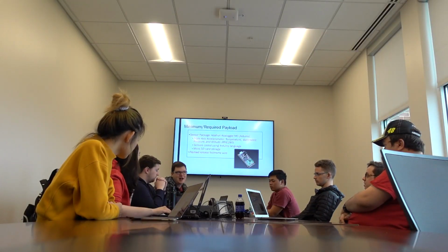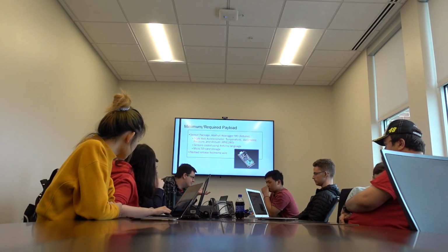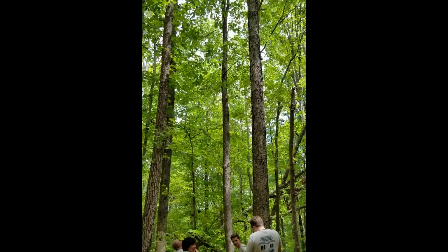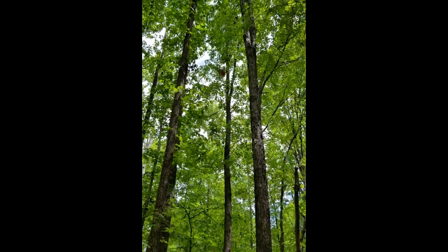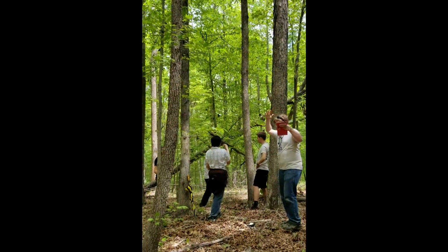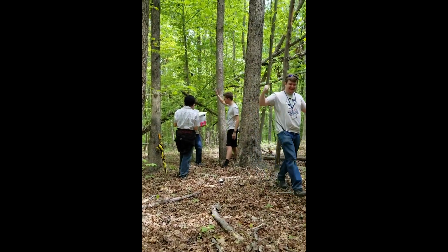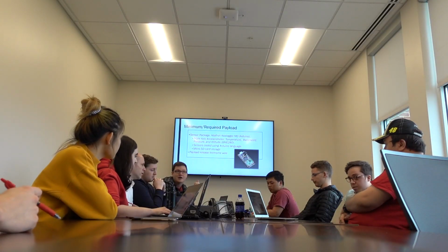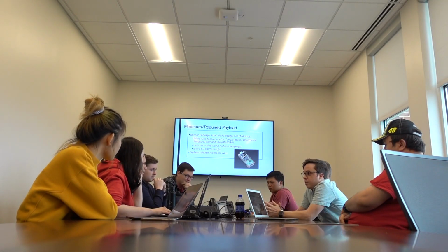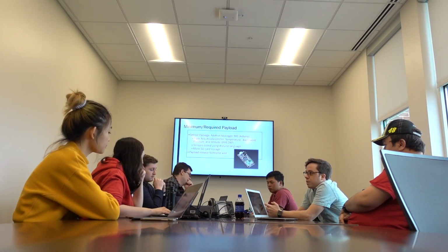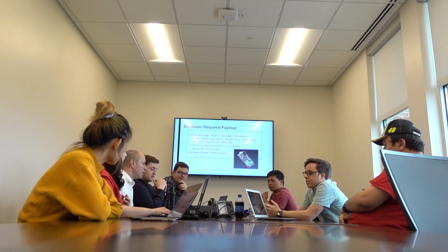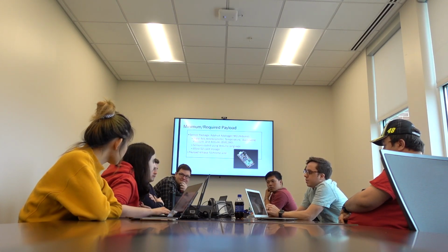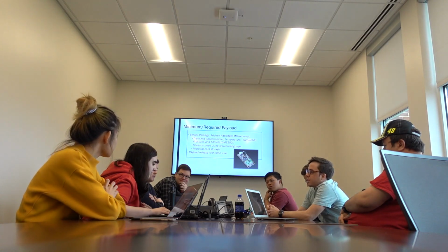To make sure that nothing could accidentally release our payload while it's in flight, we're of course using separate codes for each of our release wires that need to be put in multiple times, as well as a security feature to drastically reduce the possibility of even one wire being released during flight. Yeah, like a redundant system, exactly as Ryan was saying. That way, if something happens for some reason, the power won't go to all 4 wires and release the payload. It would only release it from one corner rather than all 4 corners.